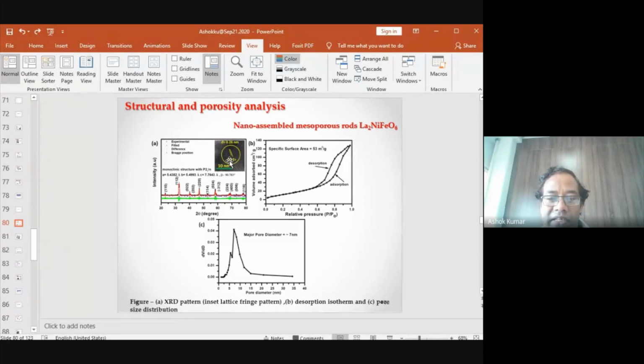Transmission electron microscopy, we do to know many things. Like the first is to know the size. In transmission, the electron has to pass to the other side, so that means the sample needs to be very thin. So transmission electron microscopy is very good for nanomaterials, because electrons can easily pass through nanomaterials. If you have bulk material, you cannot do electron microscopy directly.